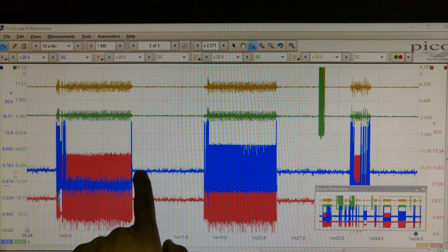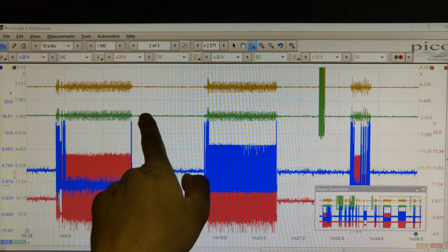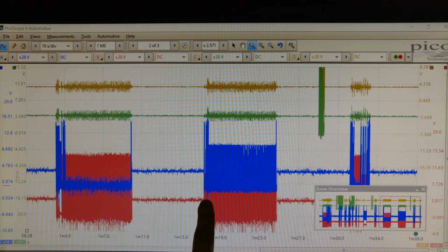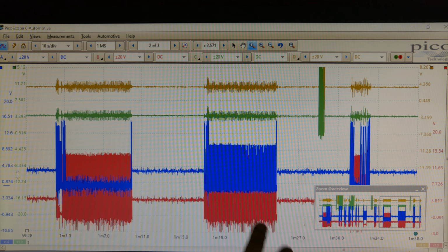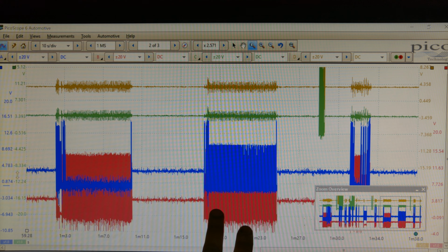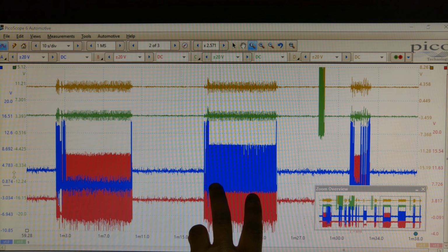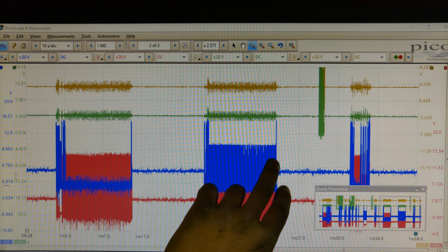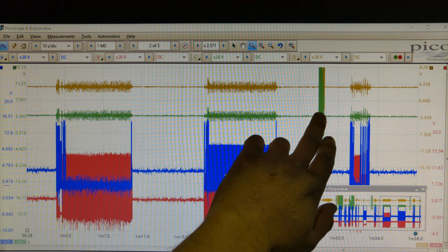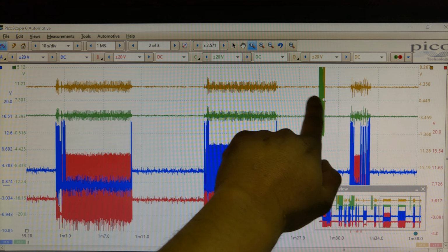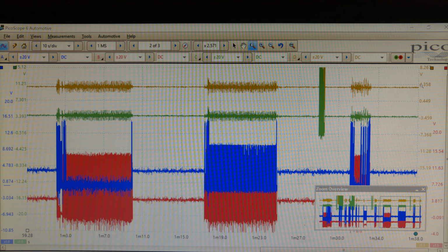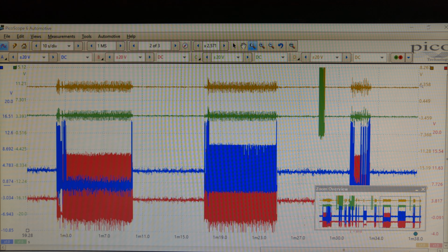And then I went to neutral. See, the lines dropped back to 4 volts again, all 4 lines, sorry. And then I went to hit drive, and on drive we got this actuator working, the bottom 2, but the top one is not working. But if you wait a little bit longer, then the top starts working up here. You can see the top start sending power and earth, because in drive you need to have both actuators working to change gears.